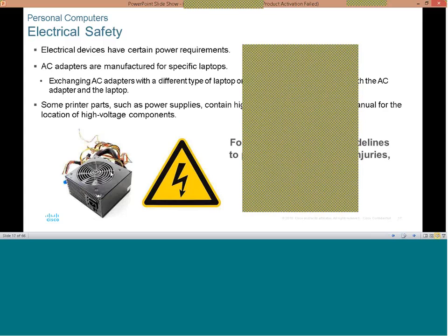Okay, I think from experience, if you have access to the right component, maybe around you there is an electronic shop where they sell those components, and they are off specification. Sure, you can change the component and it will work. One of the ways you can ascertain this is to check the output to see that it gives you the right voltage.